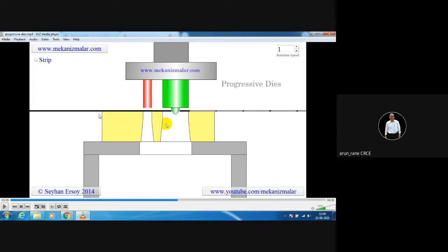Now with the help of a feeder, what will happen? The feeder will place this strip exactly at 25, but that 25 will not be exactly 0. There will be some tolerances. Maybe the feeder will position the strip at 24.9 to 25.1, plus minus 0.1. What will this locator do? The strip that comes at 25 plus minus 0.1, it will locate exactly.